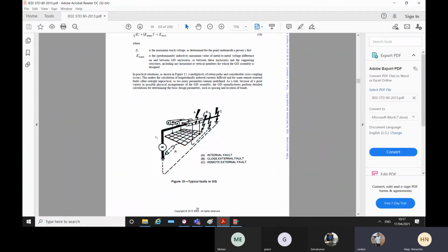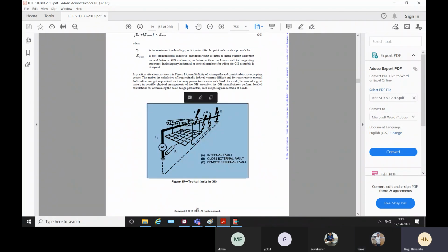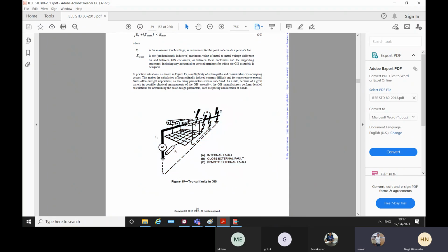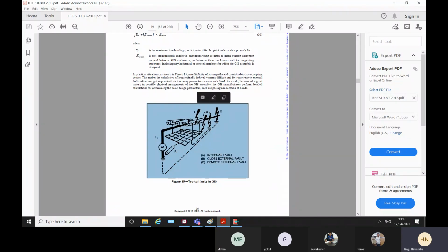But even if you want to model this or do something like this fault, it makes sense only if you model everything with the right voltage source and everything, and then you simulate the fault, or somebody gives you the right fault current for the enclosure fault. In India, people are using just 63 kiloampere or 33 kiloampere, just the circuit breaker rating, the equipment rating current. So in that case, whatever you do is a waste of time. It doesn't matter. Got it.